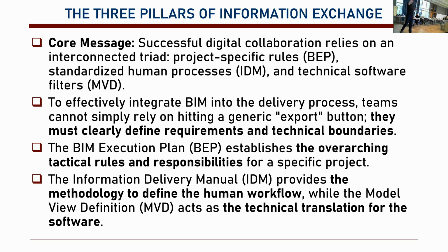We will say that the facade designer will receive from the architect the openings, the structural system boundaries, how the surface changes in the building, and then they will work on it accordingly. And the MVD is the technical translation. We will say that architects should use their model and convert it to an IFC model with these filters so that the facade designer receives only the outer skin, not interior partitions, maybe not the ceilings, or maybe they need the ceilings, but not the doors inside, etc. They don't want that.